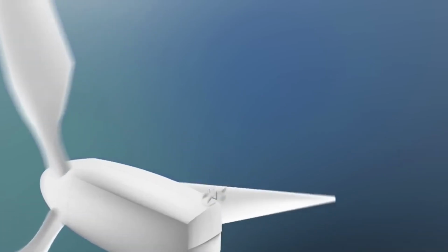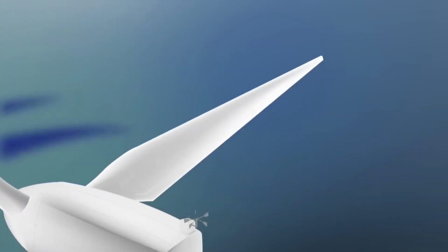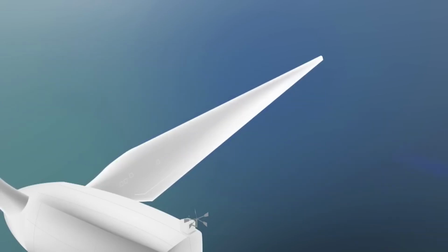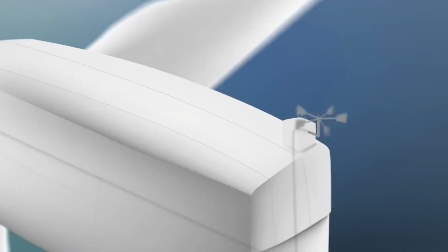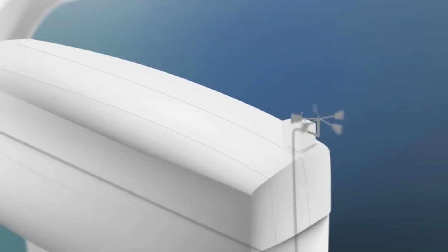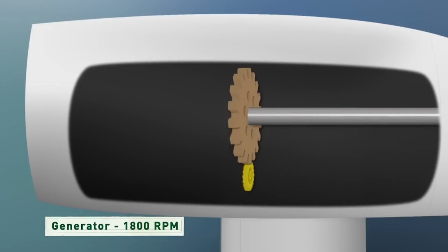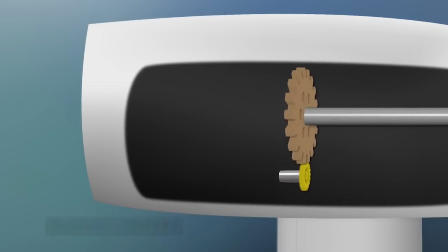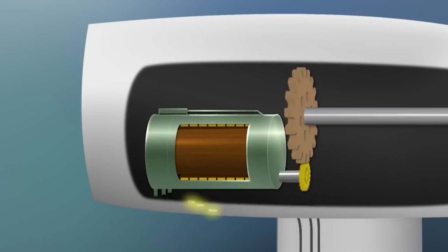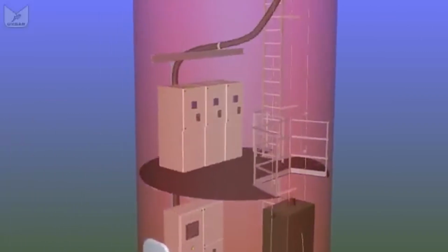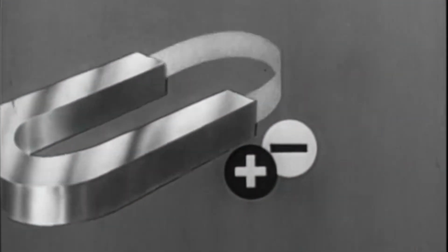So, what is wind power and how does it work? Wind power is the process of creating electricity using the energy of the wind. The process crosses 3 energy conversions. First, the kinetic energy of the wind spins the blades. Second, the blades spin the attached internal shaft, creating mechanical energy. Finally, the internal shaft spins an attached generator, which produces electrical energy or electricity. Electrical wires and cables then transport the electricity to the transformer and onto the grid for distribution.